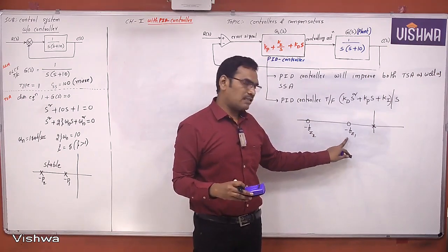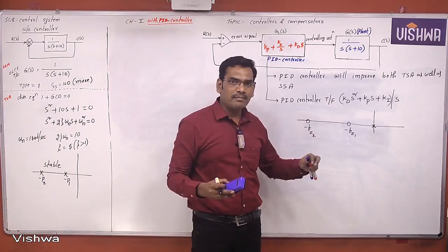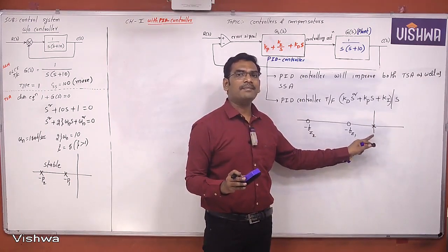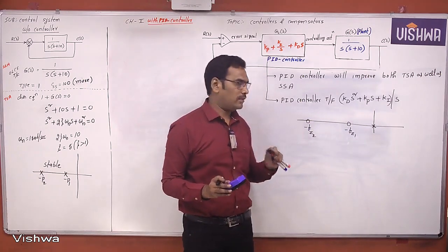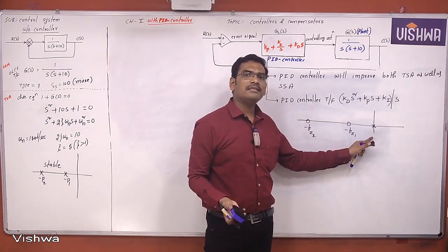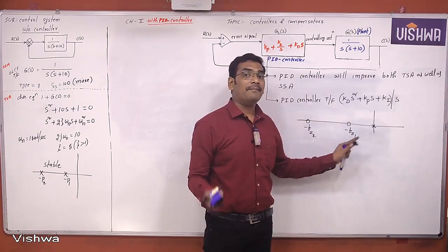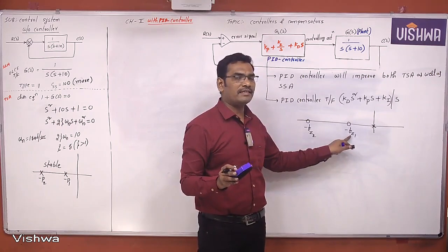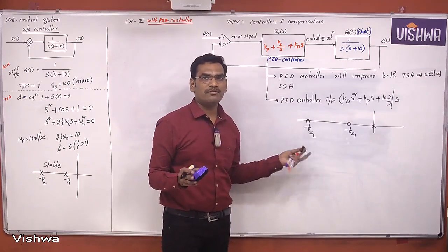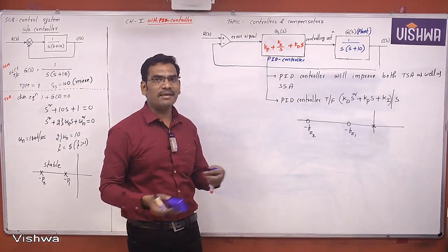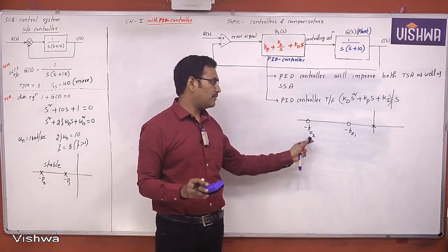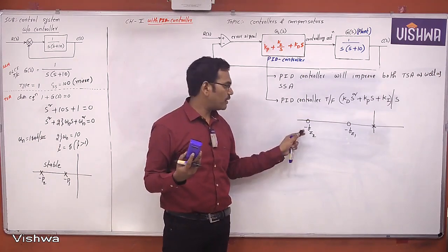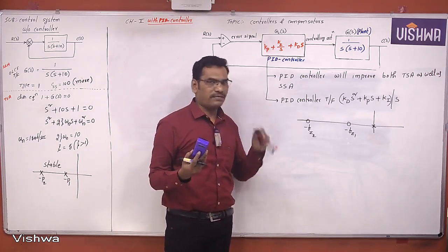The first finite zero is spent on compensating the stability effect caused by adding one pole at the origin. The second finite zero is free to improve the system stability further. The system is already stabilized, and it is used to improve the stability even more.